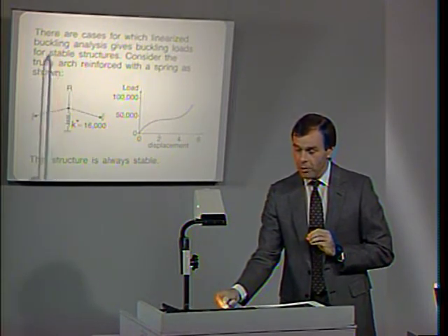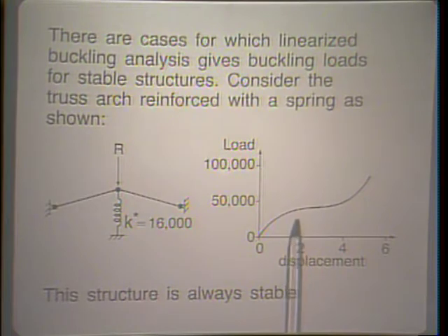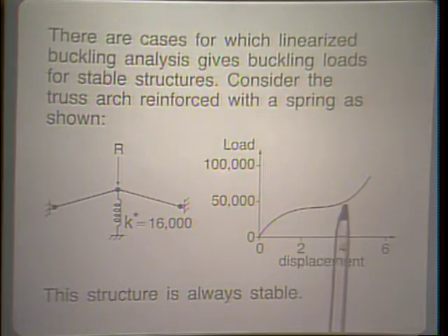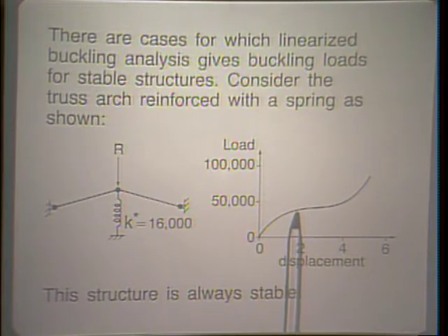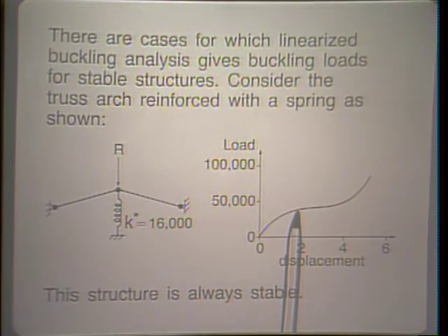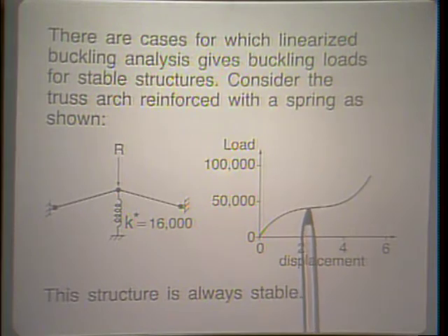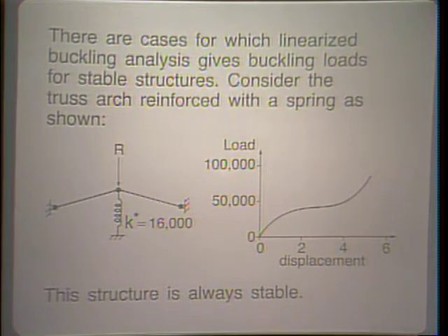Of course, when we talk about a stable structure, we really have to also define what we mean by stability. In a practical analysis, you might say, well, this displacement is just too much, and therefore I already consider this structure to be unstable at this particular location. You might want to say that depending on your design criteria. However, the one thing to keep in mind is that in this particular example, we do not have a singular stiffness matrix. The matrix stays positive all the way as we march up here on that load displacement response.